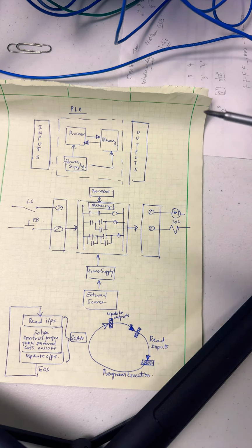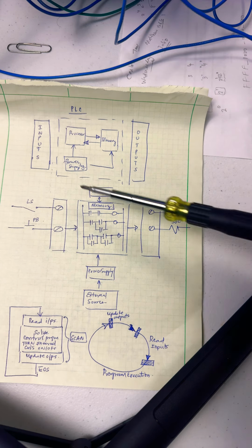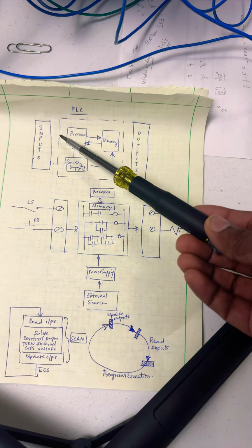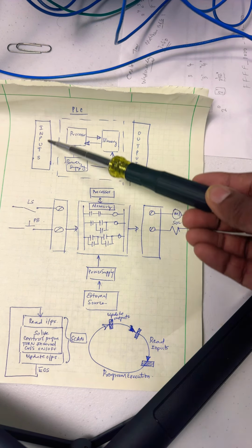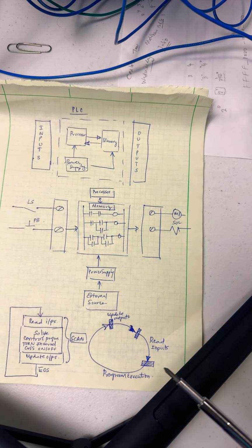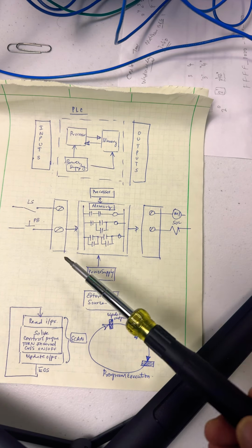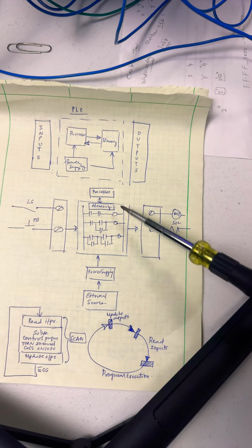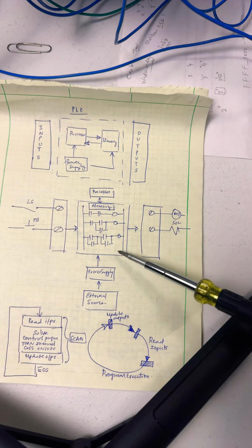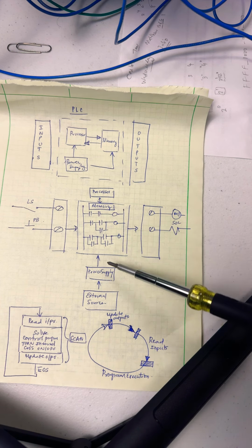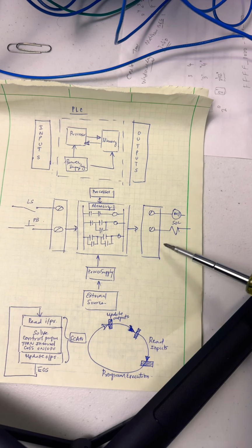So this indicates a power supply is feeding power to the processor, and a memory which the processor interacts with, and you have the input interface card and an output interface card. So this, again, is one more way of explaining where all the inputs are connected to the input interface card, and you have your processor memory, in which you have your PLC logic program running, and then you have a power supply external source, and then you have an output interface module which interfaces with the output.